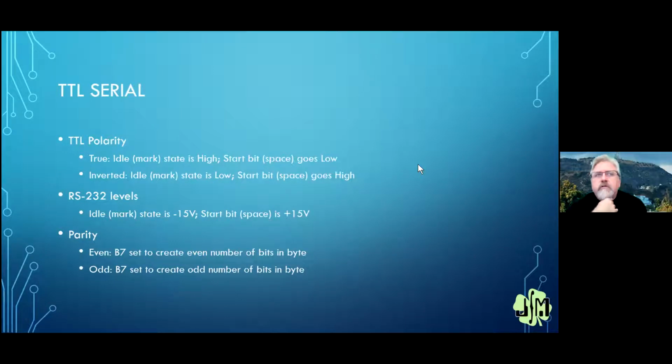Interestingly, microcontrollers have diodes built into their pins to protect them from over voltages. Now, that's all well and good, but you have to protect those diodes from overcurrent. So what we used to do in the old days, and some people still do it because I noticed that Lachlan mentioned this in the forums a couple of days ago, we would put roughly a 22K resistor in series with a serial port out of an old IBM PC, and then run that into, say, a basic stamp. And now we could get serial directly from the computer into the stamp.